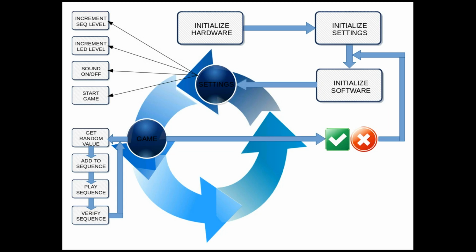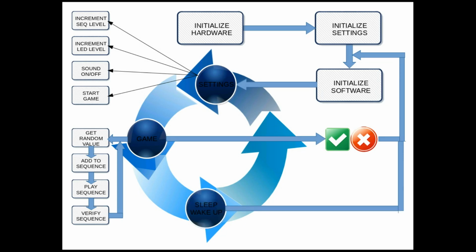So this initializes all the variables to make sure that the game can start again without remembering anything from the previous game, but it doesn't initialize the settings, so it still remembers if the sound was on or off, and it remembers the previous levels which had been selected. And the only other thing it can do is, after a period of time where the user doesn't press anything, it can go into sleep mode. And from sleep mode, when the user presses a button, it will wake up. So that's in the finite state machine as well, as a timeout period which it goes into if there's inactivity for any period of time.